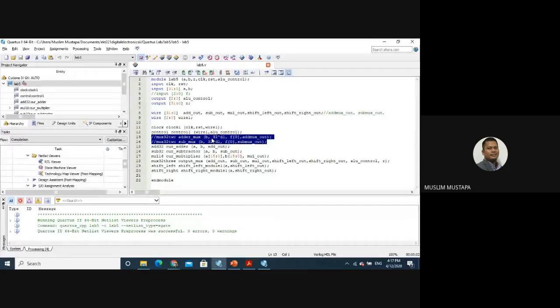The purpose of this block is if we have a carry input, which is bit 1. It's a 32-bit input, and the only one value is being used for the carry input. But we are not using it, so I'm removing the mux. The rest are the same from lab 4, and here is from lab 5.